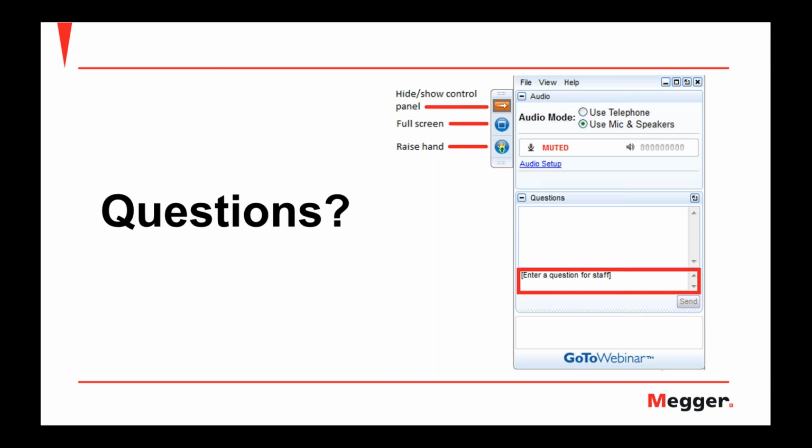Now, with that said, in standard testing, NiCads do and must have a discharge test done on them periodically, a quarter of their lifespan. That is an absolute requirement with them. Now, in between there, before you do the discharge testing, there's several tests you want to do, and one of them is measuring the straps. And most battery impedance testers, these straps will also measure the cells. And you do have something you can gain from that.